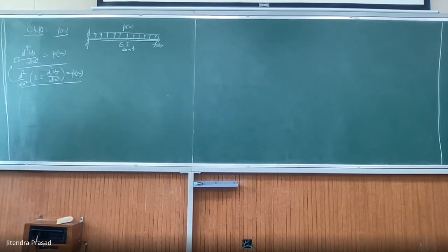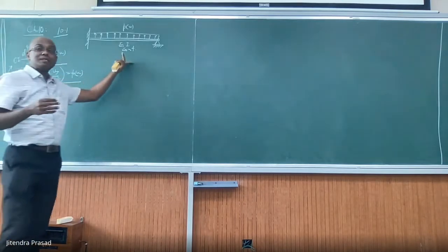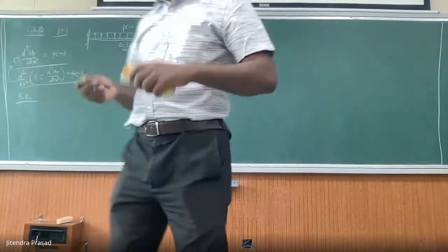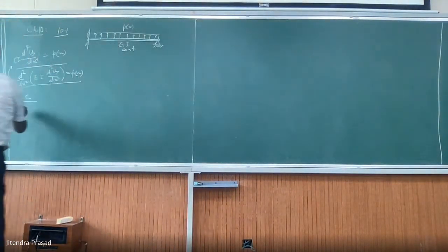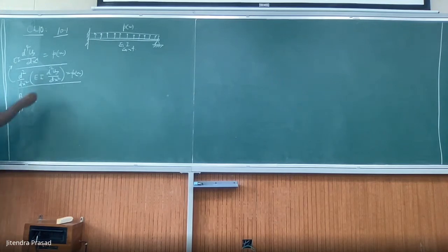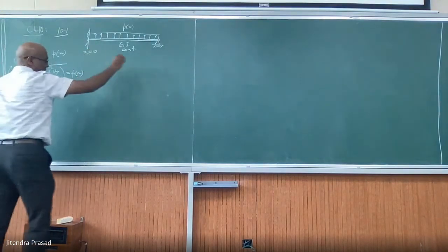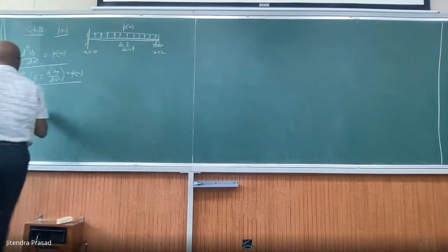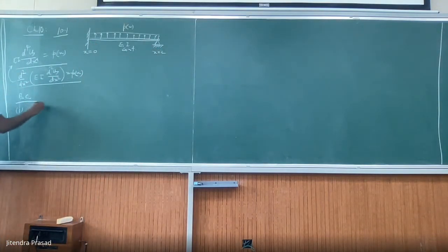Apart from the equation, you also have to know the boundary conditions. The problem is given, you have to find the boundary conditions. So you tell me, what is boundary condition number 1? Take x equal to 0 and x equal to L. First is displacement, so uy at 0 is equal to 0. Number 2 is duy/dx at x equal to 0 is also 0.